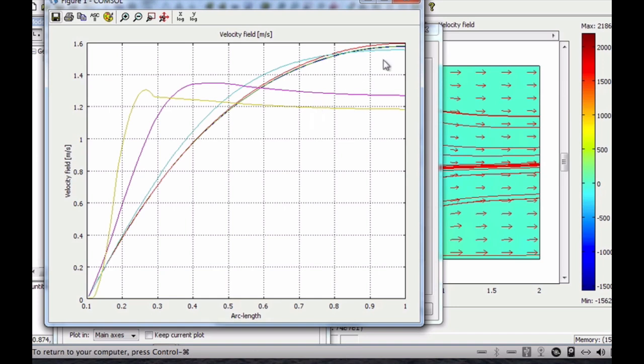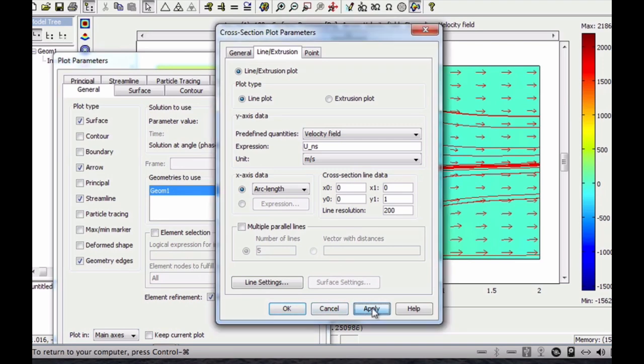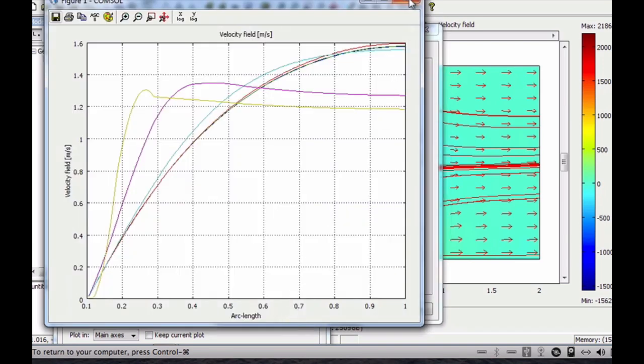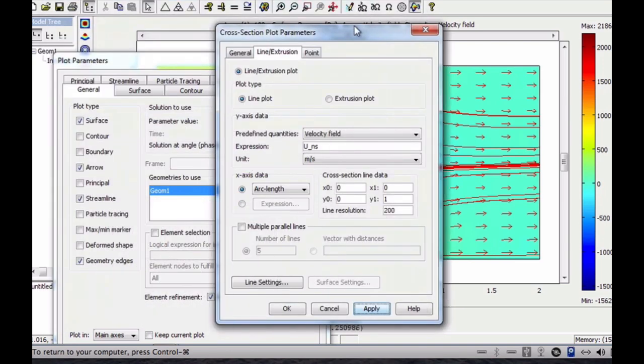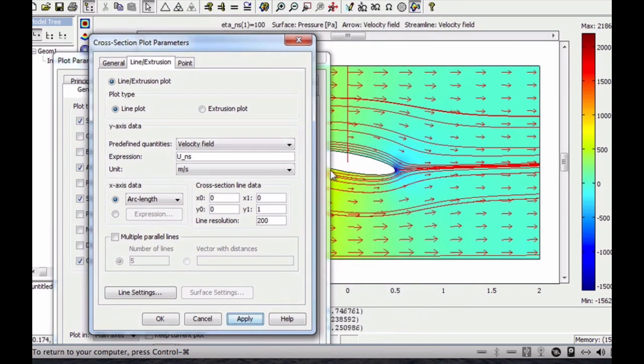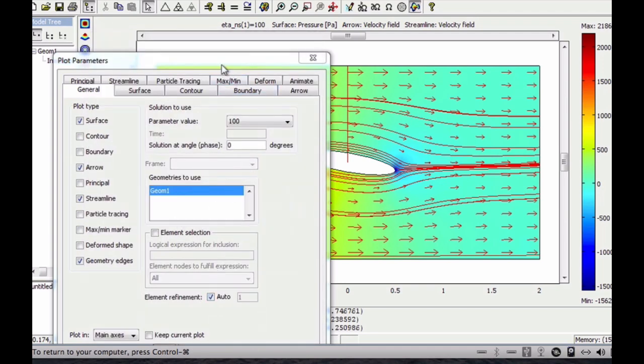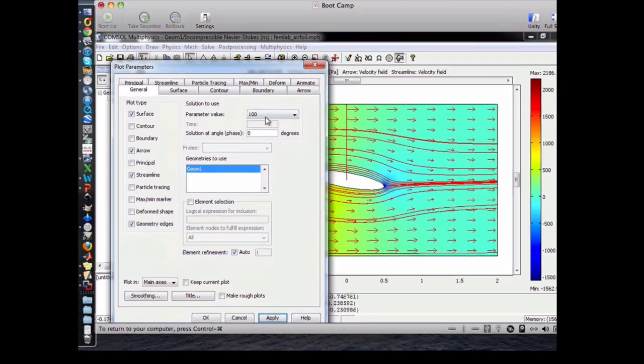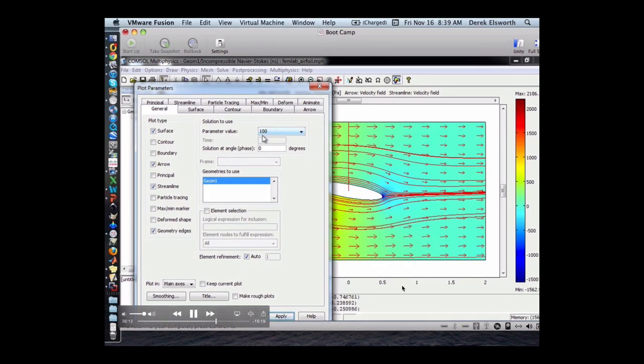And so we made the point before, it's probably easier to see this if you look at these figures here. Let's get rid of this. If you look at the magnitudes of the flow field, in this particular case, this is the flow field for the highest viscosity, which is the lowest Reynolds numbers. So we looked at the velocities, and they go to 1.6 as you get to this boundary.